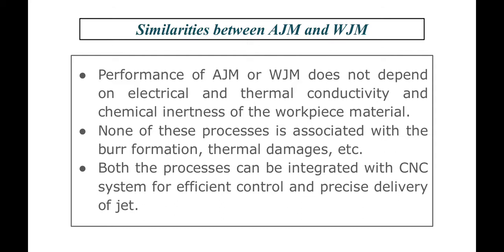Then the next point is that none of these processes is associated with burr formation and thermal damages. So we are not getting any burr formation or thermal damages in both cases. Again, both the processes can be integrated with the CNC system for efficient control and precise delivery of the jet. It also helps reduce environmental pollution, and at the same time it offers a healthy working condition for the worker. So these are the similarities between these two processes.